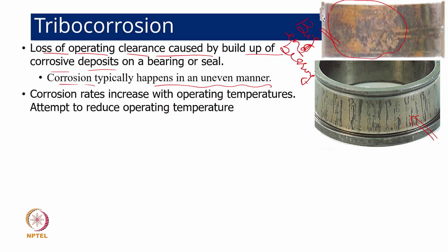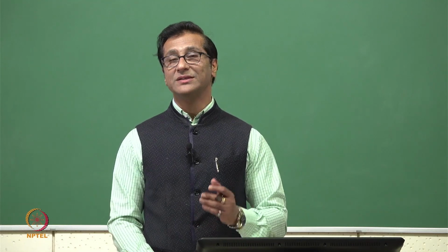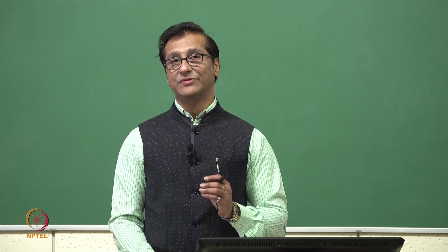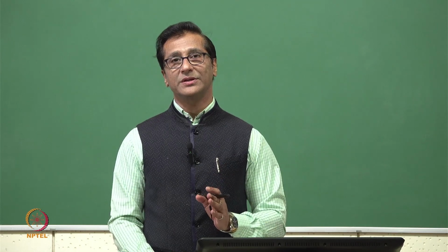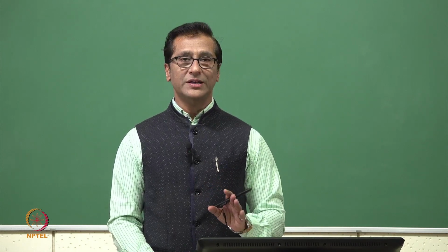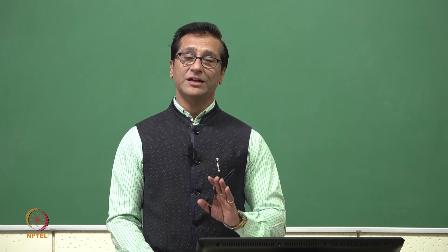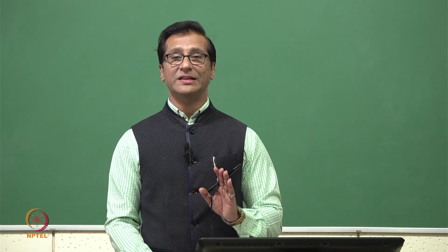They are not the same as the whole circumference. They are there, but again they are going to create more like a misalignment, some disturbance, some surface roughness. We already know that if surface roughness comes, tribology is going to get punished, or say the bearing surfaces are going to get punished because of the surface roughness. Any misalignment will create more problems: load carrying capacity will come down, friction will increase, wear rate will increase.